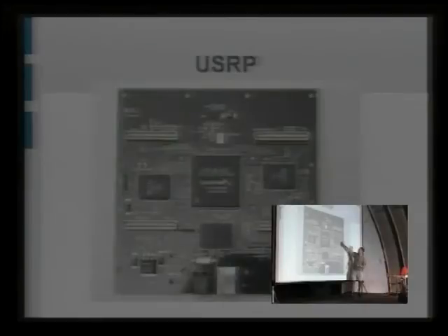And each of them, so this one has 2 lines that go to this daughter board connector. This is for the receive side, this is for the transmit side up there, and on this side it's rotationally symmetric. So this is transmit and that's receive up there. And the idea is you would plug on an RF daughter board for your band of interest onto these connectors so that you can basically transmit or receive on your frequencies of interest.